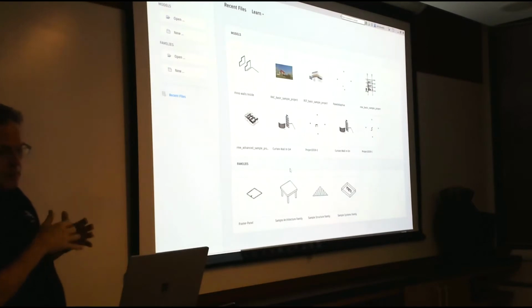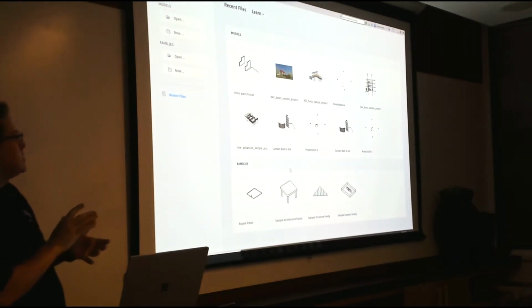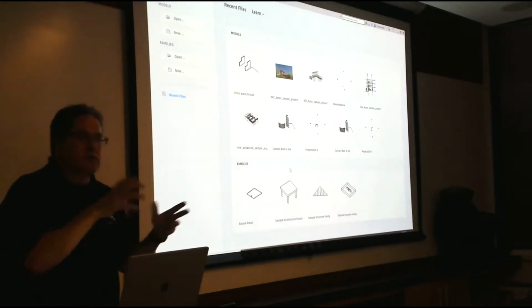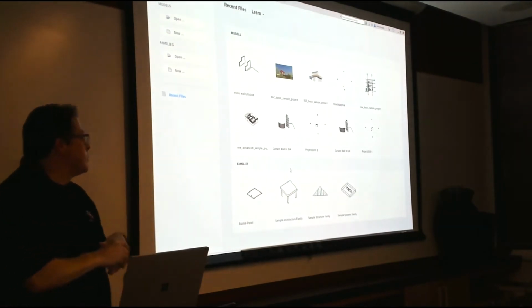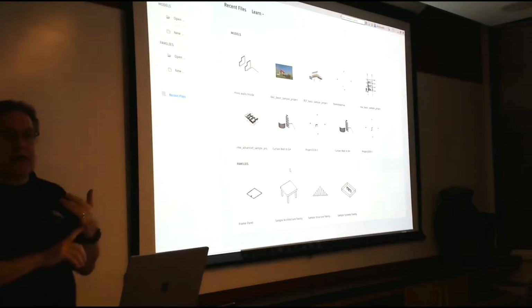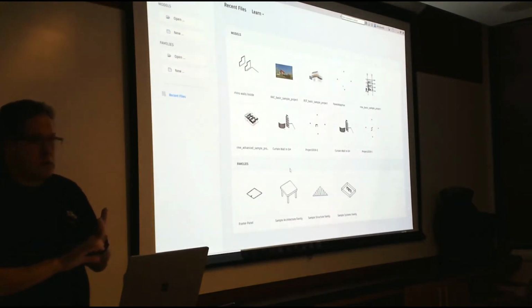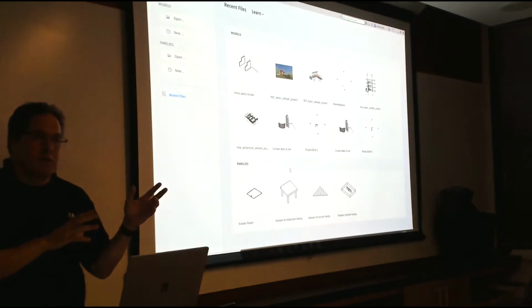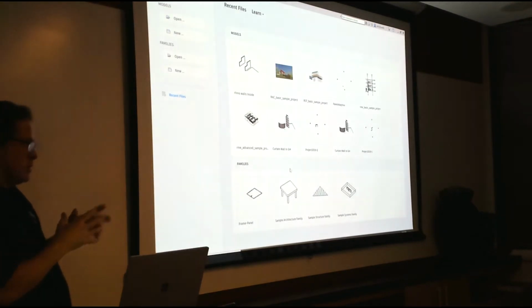So about Rhino 7, there's a few technologies I should at least mention, but I'm not going to cover them tonight. The first one is in Rhino 7, we added SubD. For those of you that know SubD, our SubDs are a little unusual in that they go to limit surface, and so you have your control net. They go to limit surface. You can edit in limit surface. Nice part about being at limit surface is it's very accurate, and there's a NURBS 1-to-1 to the SubDs, so we can convert all the SubDs to NURBS with accuracy.